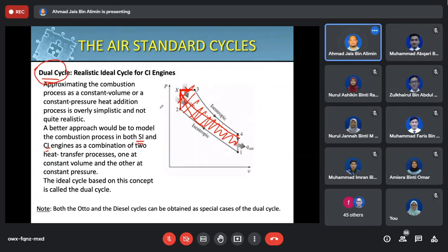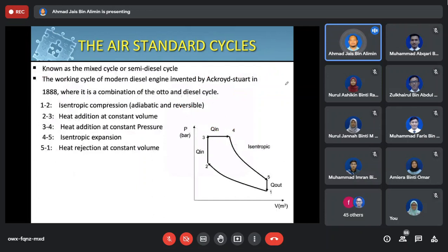So I think the most successful one is coming from the engine from Mazda. Okay, they're still pushing it towards that. Because the challenge of having this dual cycle is that you need to use two types of fuel. One that is compatible for spark ignition, and another type of fuel you can use at high pressure, which is during the compression ignition cycle.